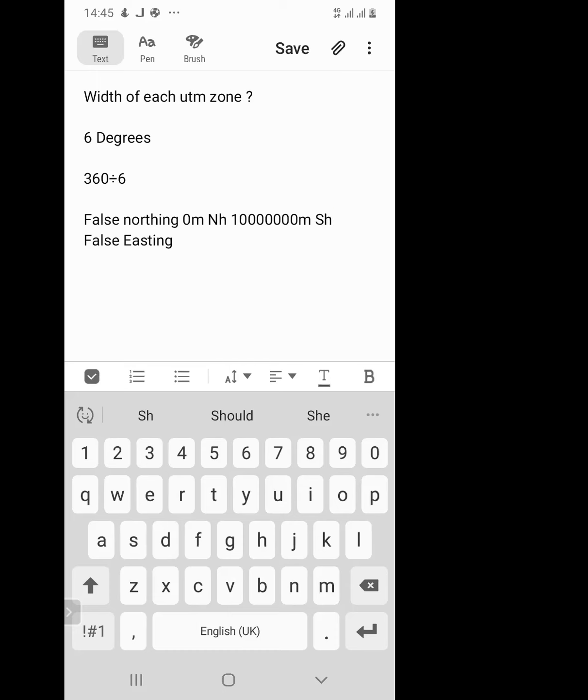But you see, we avoid negative values in surveying and survey engineering, not civil engineering, survey engineering. And of course, survey engineering is civil engineering. So we try to keep the northern at a very high value, so that we get positive values down south. Are we good?